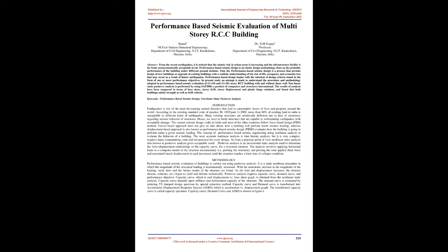In the present study, an attempt is made to understand the procedure and methodology adopted in performance-based seismic evaluation of G+10 and G+20 storey R.C.C building with and without shear wall. Nonlinear static pushover analysis is performed by using SAP 2000, a product of Computers and Structures International. The results of analysis have been compared in terms of base shear, story drift, story displacement and plastic hinge rotations, and found that both buildings satisfy strength as well as drift criteria. Keywords: performance-based seismic design, nonlinear static pushover analysis.